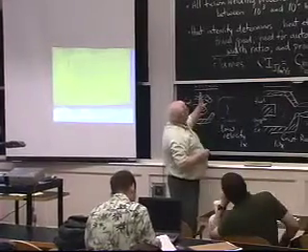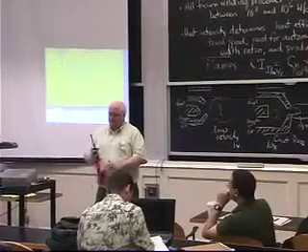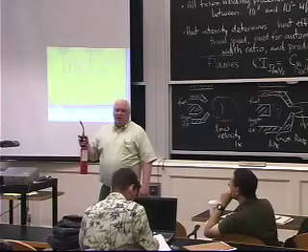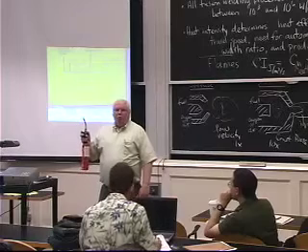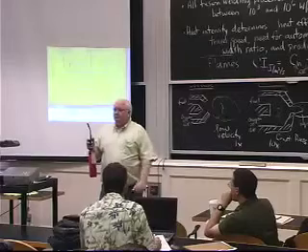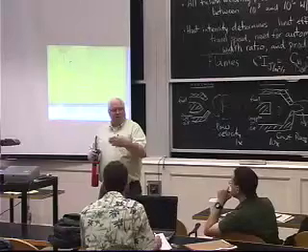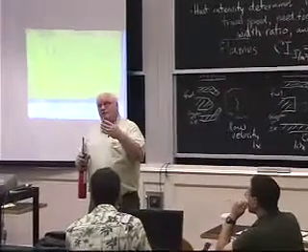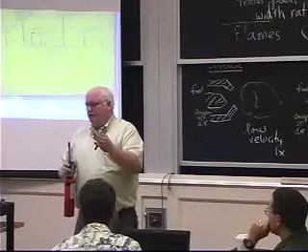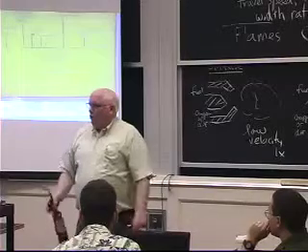It turns out for this premixed flame, this is an air fuel flame. It's got a heat intensity of about 100 watts per square centimeter, but only about 1 watt per square centimeter of surface actually gets transferred, maybe 2, into the metal. So 1 or 2% of the total heat generated chemically is actually getting into the metal. Does anybody have any idea why it's so inefficient?